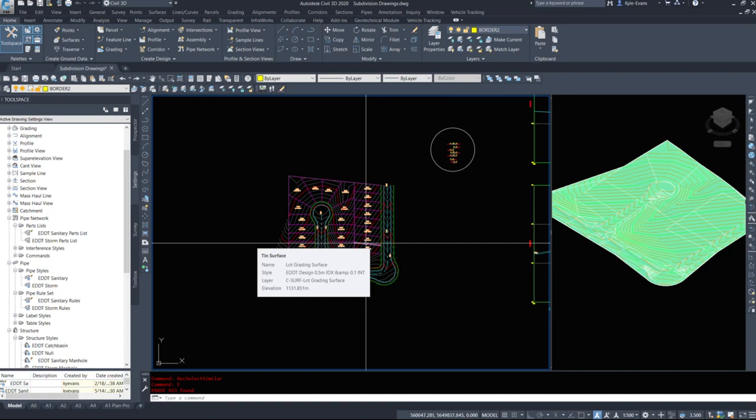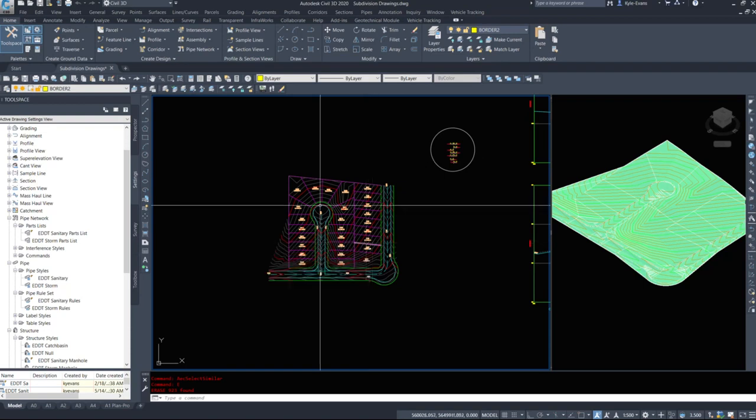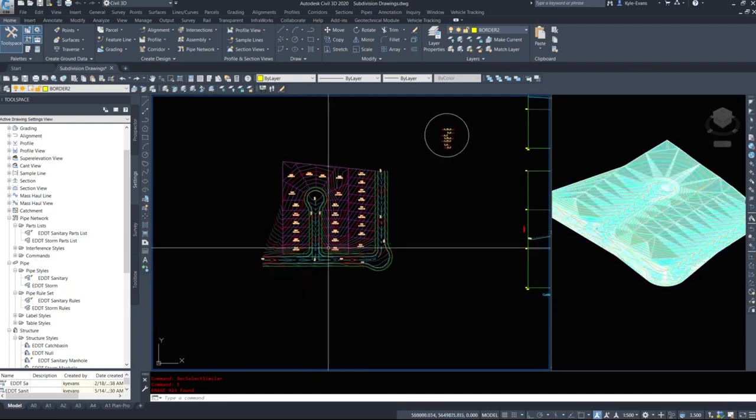So with our rainwater, we're going to work on our storm design. We're going to size our manholes and catch basins. We're going to worry about any rain that falls during a storm. Sanitary flow will be what's coming from your house, and we're going to find out that these flows are different sizes and we need different size pipes. And possibly in another video, we are going to look at our fresh water coming from the city. The sanitary and storm will be gravity drain pipes, and our water is going to be built under pressure pipes. And again, these are probably going to be two different videos just due to the sheer amount of size.